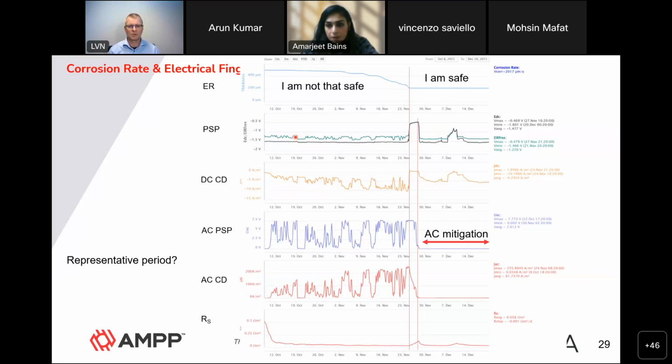Yes, the probe can be used in many ways. The most informative is when you have a continuous monitoring or data logging of the probe. And if you see the data every day by remote monitoring, you will have instant access to the data. You can also use it in such a way that you have installed the probe and you connect it directly to the pipeline without any data logger. And then maybe every 3 months or every 6 months or every 12 months, you come back to see what is my thickness of the probe now.